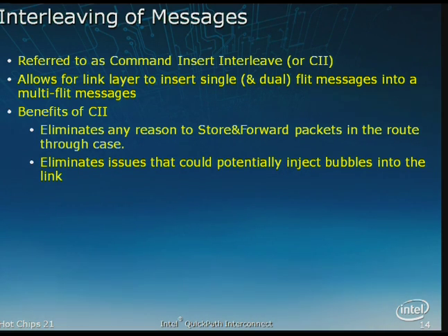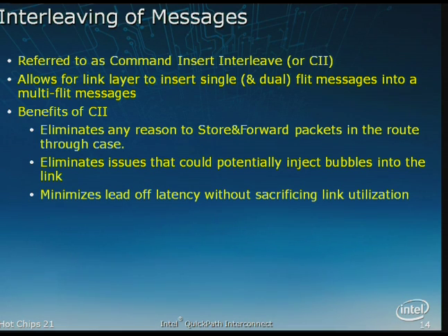This also allows us, as memory comes streaming out of memory controllers, if the memory runs at a slightly different frequency, or there's a correctable bit flip in the memory subsystem, if there's a bubble, we don't have to bring the entire 64 bytes in before we start sending it out. As it arrives, we start sending it out. Again, no store and forward, which minimizes lead-off latency. This is very important in our EP systems, which are the Xeon 5500s and things like that.